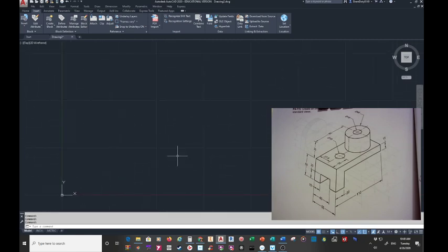Okay, so first things first, AutoCAD doesn't really care about units as far as what's an inch, what's a millimeter. When you draw something in AutoCAD, if you compared a metric and inch drawing, the metric drawing is 25.4 times bigger than the inch drawing is. It doesn't matter if you were thinking of comparing and converting your measurements. In AutoCAD, it's a scale, and 25.4 is the difference.